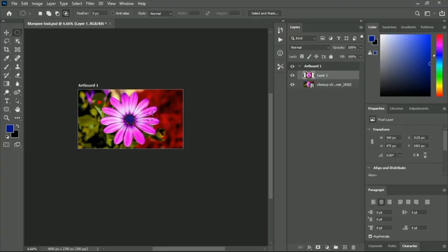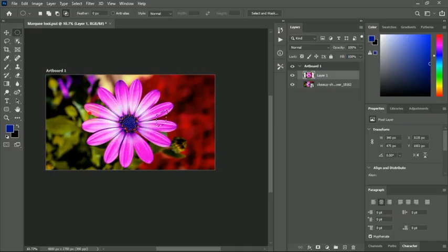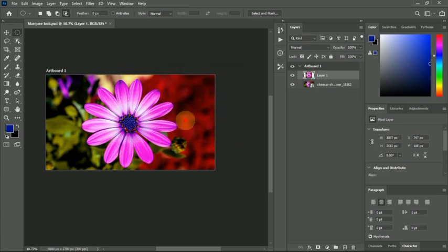This one here is intersection. It will select where your selections intersect, like for example, it will select what is inside our first and second, as you can see here, that part. But when you now select outside this one rectangle, you will receive an error. It is supposed to bring an error since there is no intersection there, as you can see here. That is these features here.